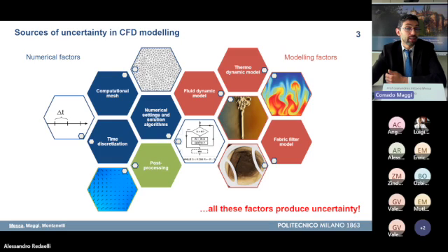And so there are a lot of factors decided by the users, which introduce uncertainty to the CFD results, which relates with the numerical analysis processes. This includes, for instance, the solution algorithms, the difference schemes, and, very important from the point of view of the users, the computational mesh used to discretize the space domain and the time-stepping schemes.